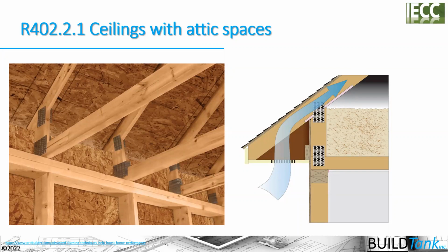And we're not going to go into it, but there are also requirements for how that attic eave baffle is actually installed in the 2021 IECC that are different than in the previous versions of the IECC. The biggest difference is that you're required to have continuous soffit eave baffles, regardless of if you have skip or continuous soffit venting there, so that we get that air moving up and over the insulation and not penetrating the insulation.